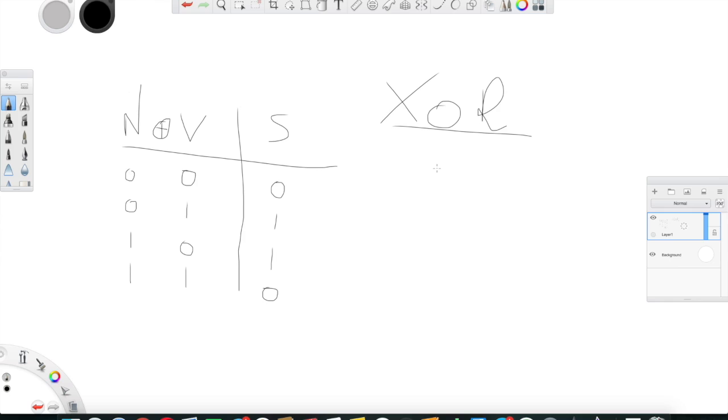Okay, so let's actually understand why the sign bit is the exclusive OR of the negative flag and the overflow flag. As I told you, the sign bit represents the expected sign of the output, not the actual sign. The actual sign is represented through the N bit. So the N bit is 0, meaning that the number is positive. And the overflow flag is 0, indicating we did not have an overflow. Therefore, the sign should have been positive, because the actual sign is 0 and I do not have an overflow.